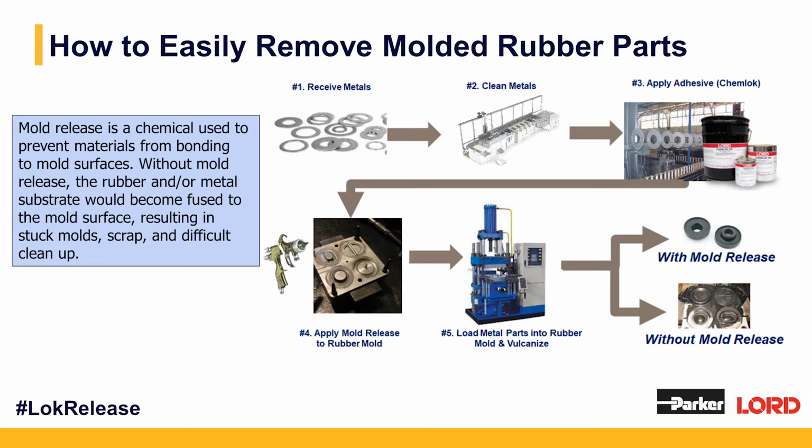Likewise, when you apply mold release to the mold, the best practice is to apply light coats in multiple directions, allowing the solvent or aqueous carrier to flash off between coats. Make sure the entire surface of every cavity is equally covered by changing the angle you spray at for each light coat so the shadowing effect is minimized. If the mold release product is applied too heavy or too light, you will end up with parts that don't meet your requirements and ultimately don't meet your customer's requirements, as well as potential downtime to clean a dirty mold.